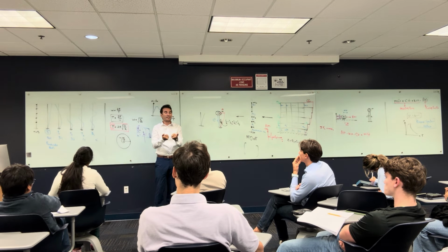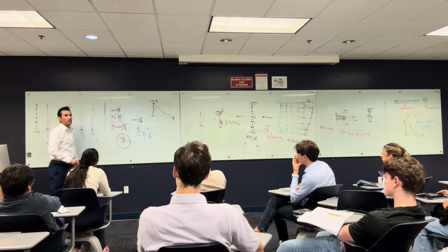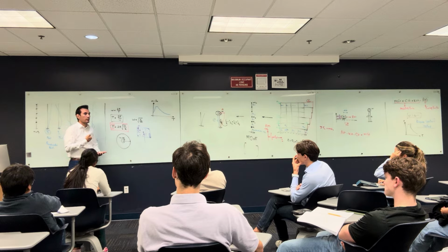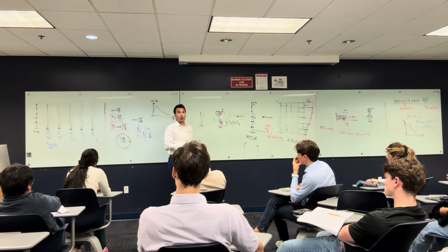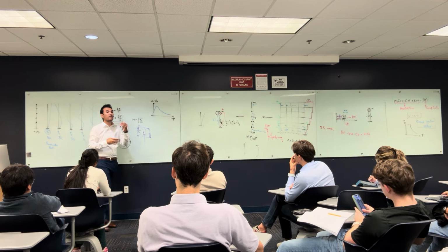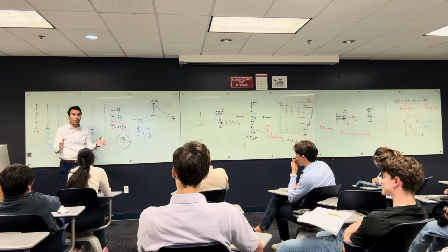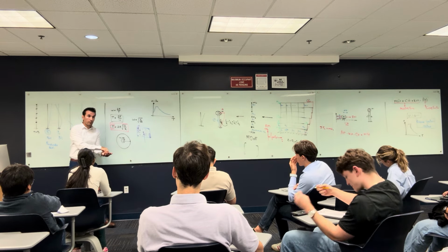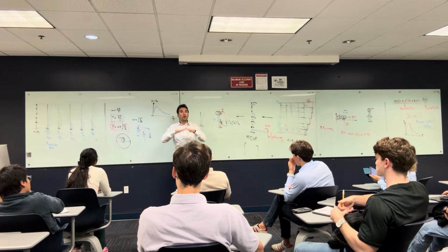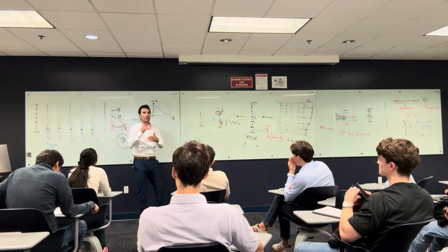So every structure has a completely different period. However, sometimes we simplify: this structure is the same as this structure, so they are going to have the same period. But in real life, none of the structures are going to have the same period because they have different soil underneath them, different structural elements, and different loading at the time of the earthquake, because this mass includes what we call the sustained mass in the structure, which is definitely the dead load, because the dead load is not going anywhere, and the live load during the earthquake. When we design for gravity load, we assume all the live load is there. But when the earthquake happens, we go less extreme, assuming that not all the live load is there.